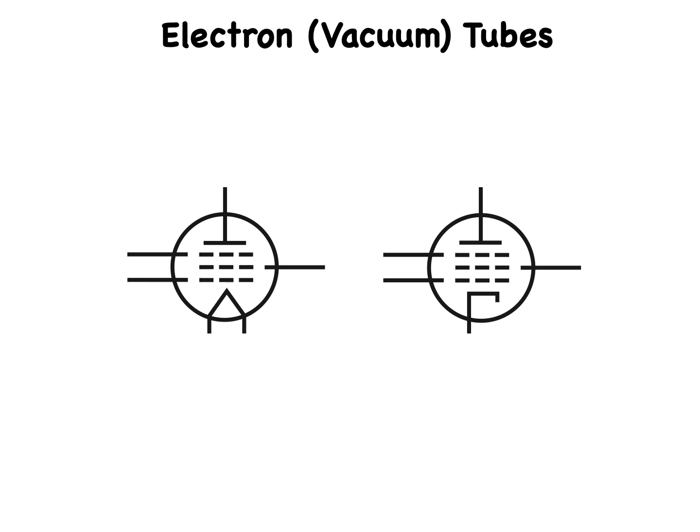This shows symbols for the so-called pentode tube, which has 3 grids and a total of 5 elements. In the pentode, the second grid, going from the bottom up, is the screen. And the third grid, just underneath the plate, is called the suppressor. Again, the left-hand symbol portrays a device with a directly heated cathode, while the right-hand drawing shows a device with an indirectly heated cathode. In all the vacuum tube symbols shown, electrons normally flow from the bottom up.